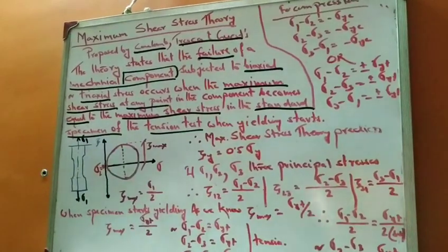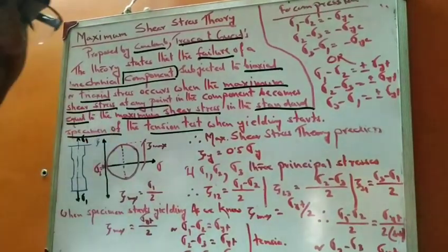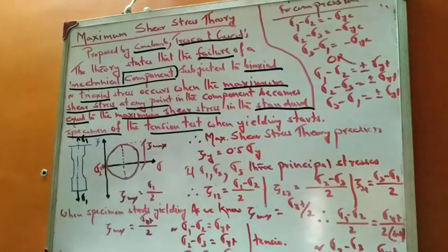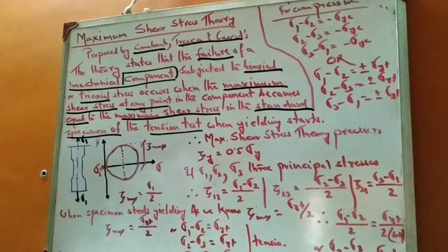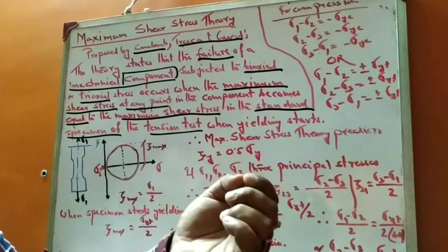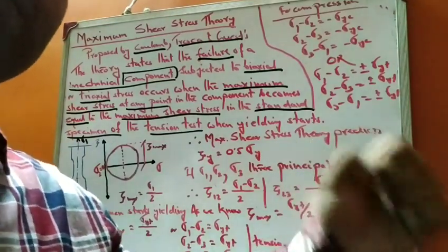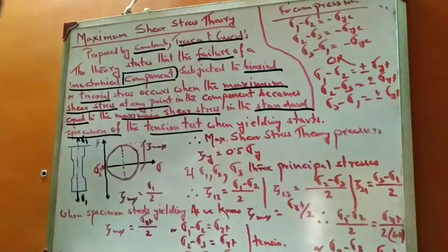So when anywhere in this component the maximum shear stress becomes equal to the yield stress of a standard tensile specimen, then fracture will take place.